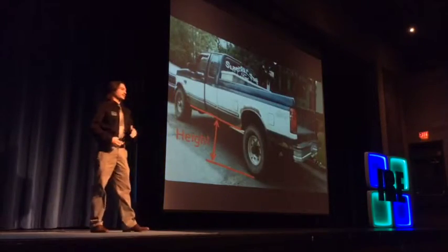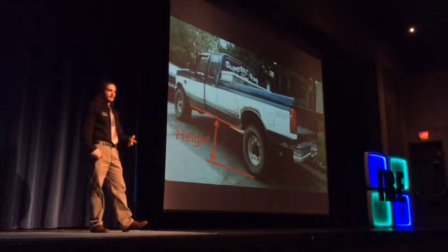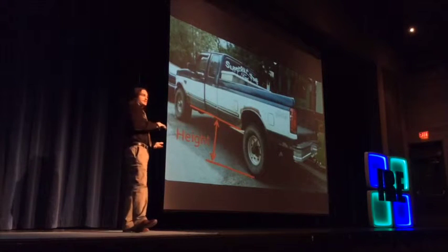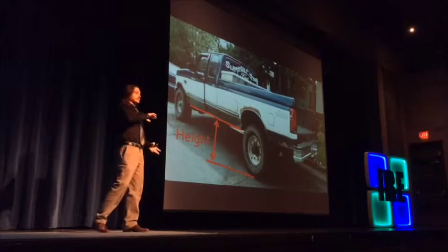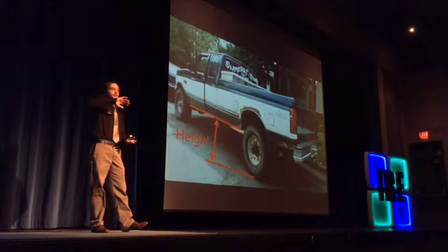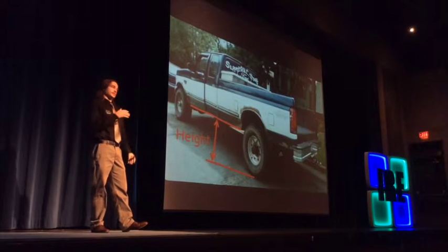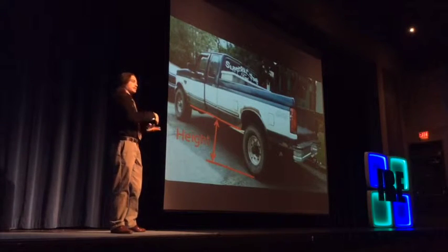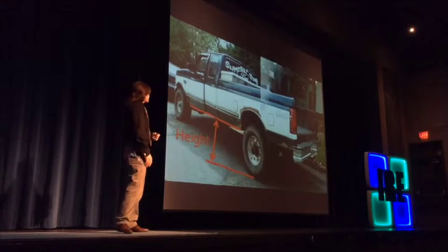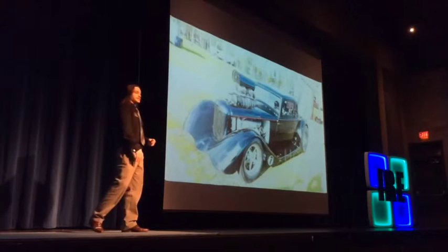The next thing you're going to have to worry about is your ride height. The ride height is going to determine the center of gravity of your vehicle. The higher your center of gravity, the more leverage the mass is going to have on the vehicle to roll when you come into a corner. And because you're drifting, you're going to have an excessive amount of body roll because all you really do is turn. So then the last criteria is going to be performance.